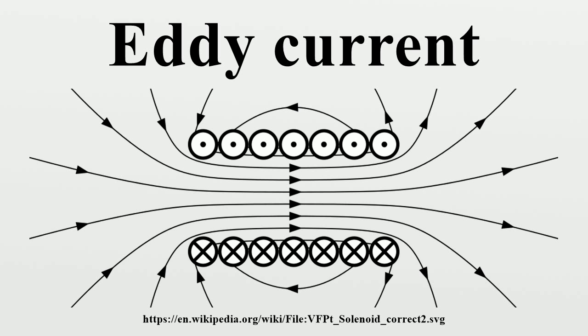This eddy current is formed by the movement of the wheels. So, by Lenz's law, the magnetic field formed by the eddy current will oppose its cause. Thus the wheel will face a force opposing the initial movement of the wheel. The faster the wheels are spinning, the stronger the effect, meaning that as the train slows the braking force is reduced, producing a smooth stopping motion.